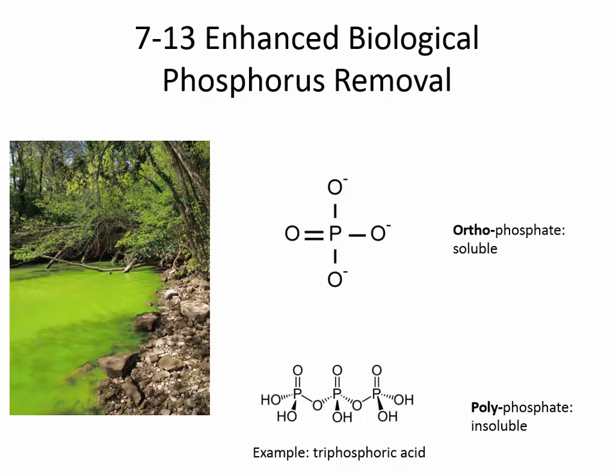And the reason why they did that was that the orthophosphate prevented the hardness. There was a lot of iron and manganese in the water in Indiana because it was groundwater, and so they'd add a little bit of orthophosphate, because if they didn't, then the iron would start to oxidize, and someone would fill up the tub with water, and the water would look orange or black to them, and people think, oh, the water shouldn't be orange.